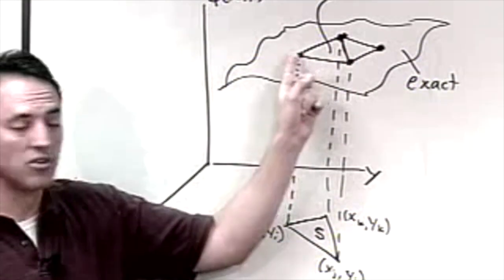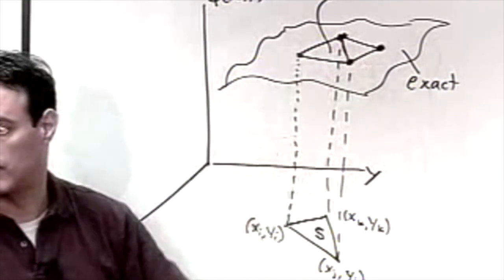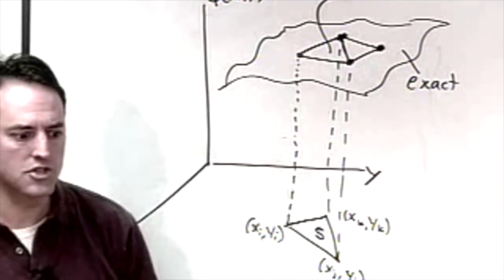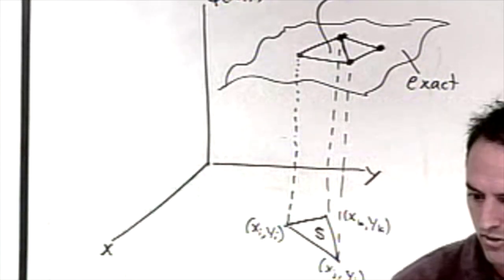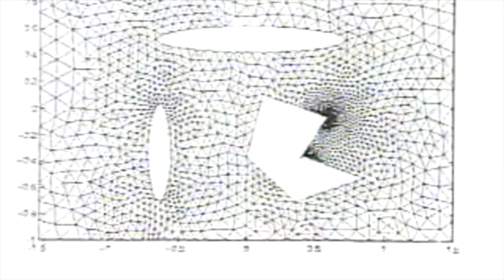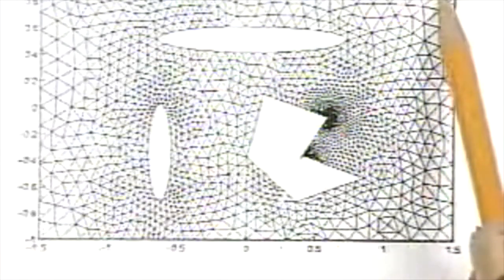This guy couples to this guy because they have these common triangles. Okay? And briefly, going back to this picture again, same idea here. When you discretize this, here's this solution surface above this thing. A point right there connects to a point over here, because this guy is connected to this triangle. All these triangles are connected together. It's the Kevin Bacon problem to an extreme, because you connect all the way through, and all these guys are connected through their neighboring triangles. So no point is really isolated.